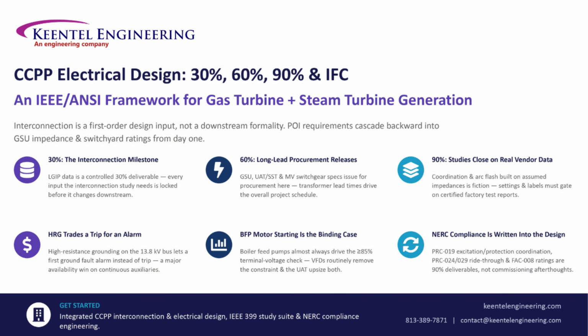At 60%, the long lead procurement releases, GSU, station service transformers, and medium voltage switchgear specs go out for order because transformer lead times are what actually drive the schedule. 90% is where the studies have to close on real certified vendor data. A coordination study or arc flash analysis built on assumed transformer impedances is fiction, and the plant inherits that liability at commissioning. A few details matter enormously along the way.